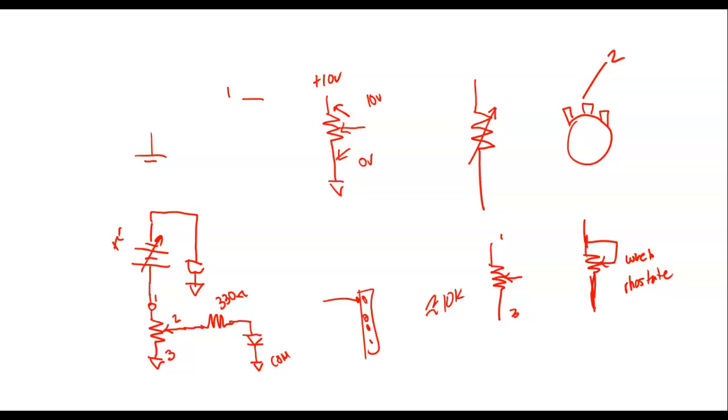These are quarter watt potentiometers, so we don't need to get too much current flow through them. And these are 10K pots. Once you get it wired up, set the supply at 5 volts. Don't use the fixed 5 volts; I want you to use the variable and get used to using that. Once you set that to 5 volts with your meter, you're through with adjusting the supply. Then you're going to adjust your voltage with the potentiometer.